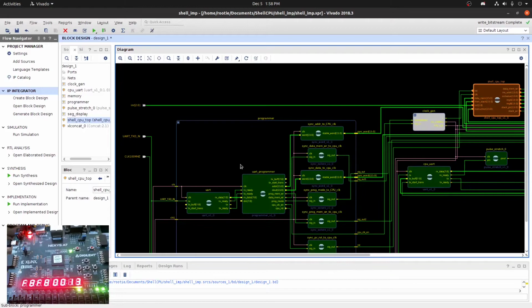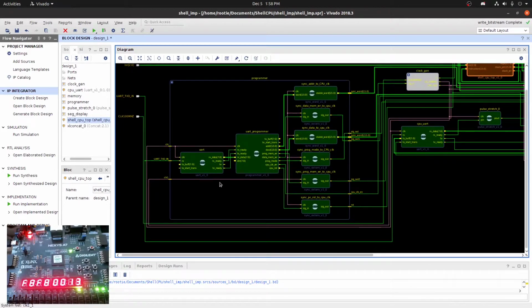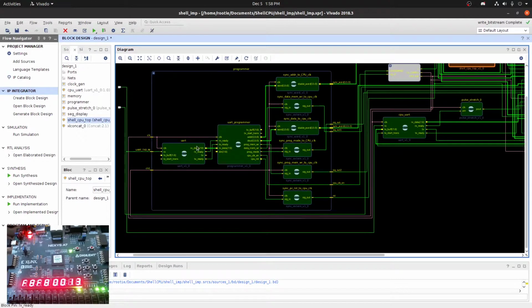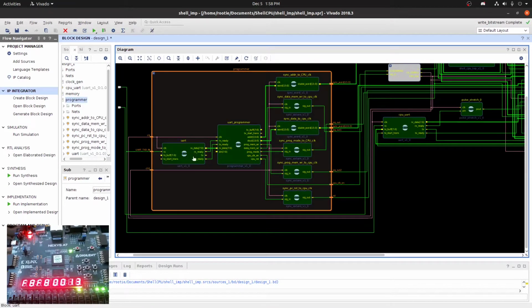When I was loading programs over through my terminal, over Python, through the serial port, this is how the CPU was getting it in its memory. Your UART controller is just sitting there listening to the signals coming over, and it's taking them from serial and converting them to 8-bit registers of received data out.